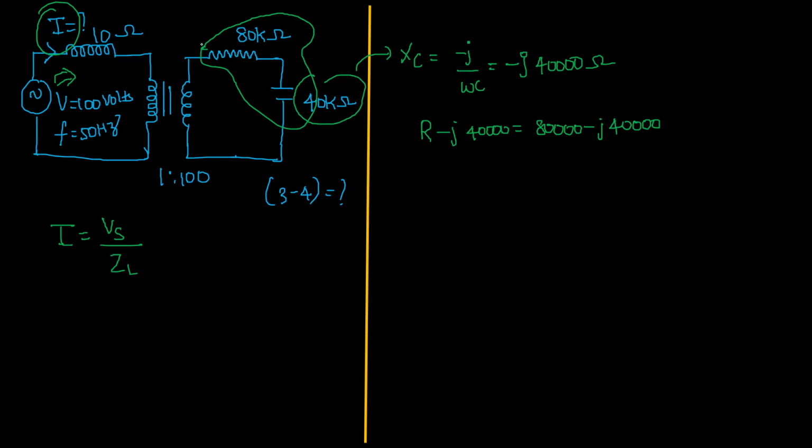So we transform the secondary loads of the transformer to the primary, and then sum the loads on the primary and the secondary, and substitute that total value here, then we will get the answer. Because voltage is readily available, but which is missing here? Total impedance is missing. Let us see.